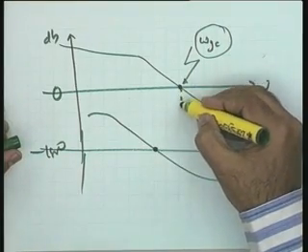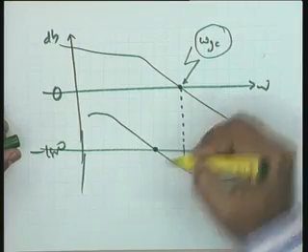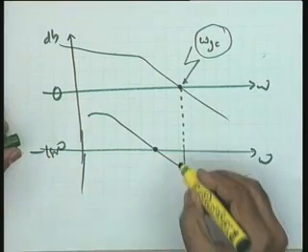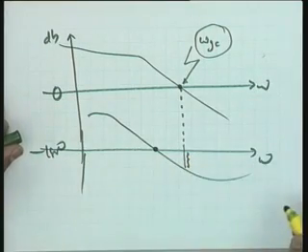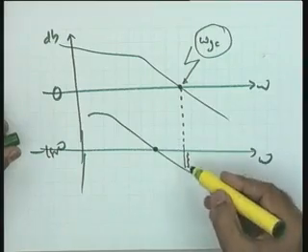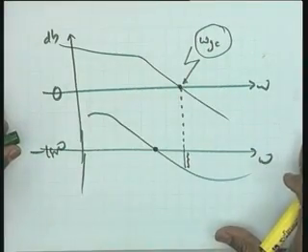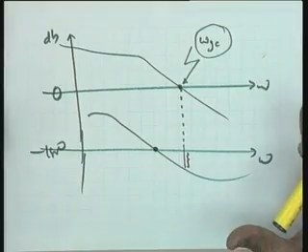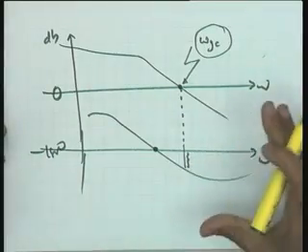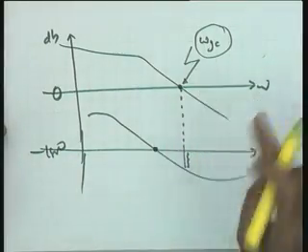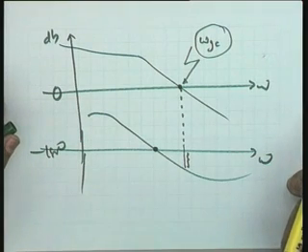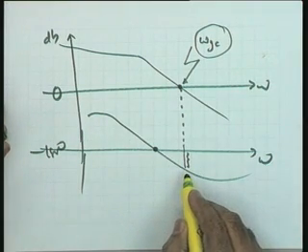Now, look at the phase margin. So, at this particular point, if I measure the angle with respect to minus 180 degrees, this is your phase margin. In this particular case, the phase margin is negative. It means whatever plot I have made over here without any transfer function in front of me has turned out to be the open loop plot for a closed loop system which will be unstable, because the phase margin is negative in this particular case.